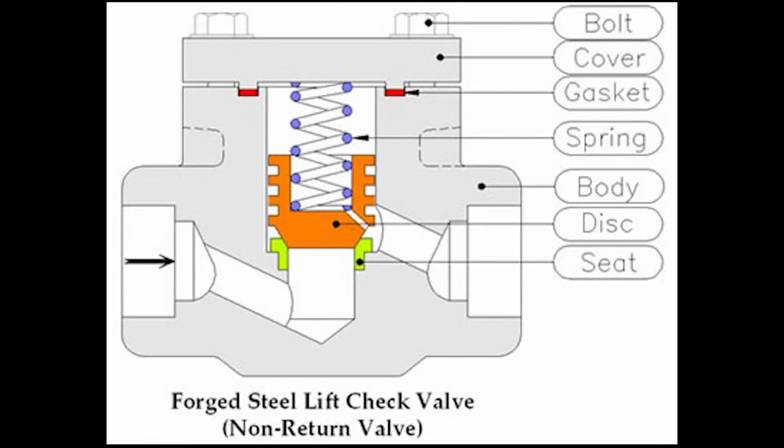Non-return valves have two openings in their body, one for fluid to enter and another for fluid to leave. They work automatically, using a movable valve stop which creates an internal seal to prevent backflow. The valve stop can be either spring-loaded to keep it shut, or otherwise reverse flow is required to create the seal.